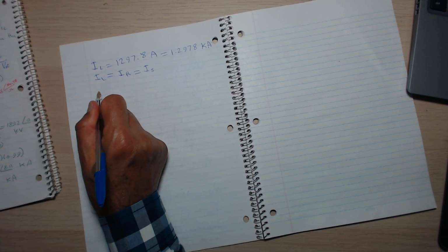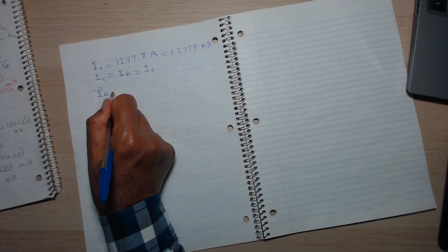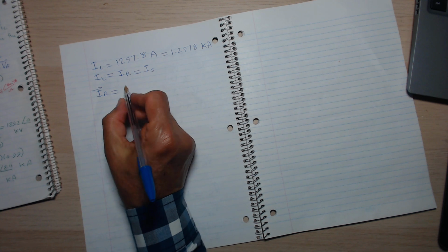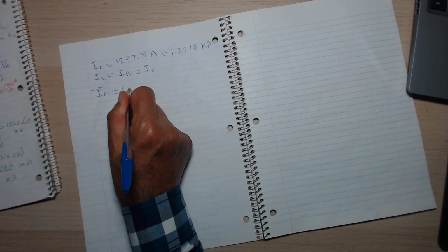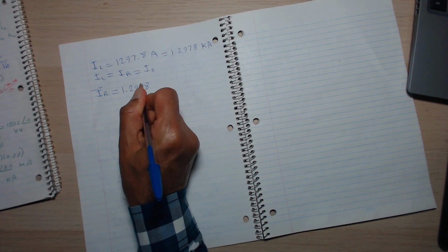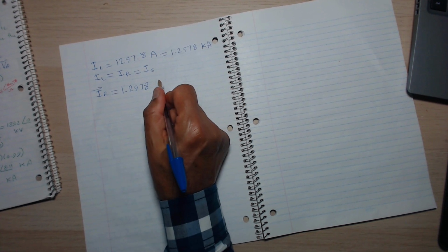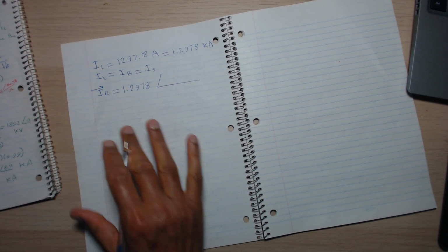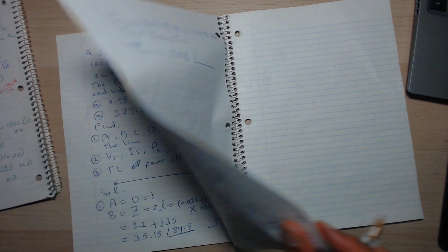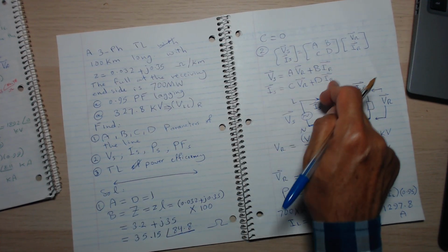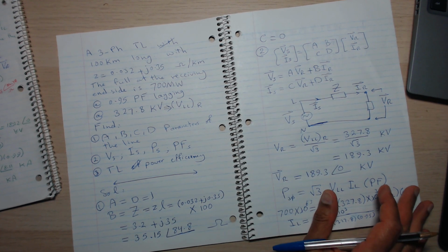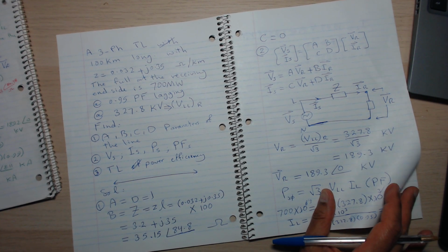So we found IR, but this is only the magnitude of the current in kilo ampere. We want its angle, we want it as a phasor quantity, because these two formulas are valid only when you use the currents and voltages as phasor quantities,